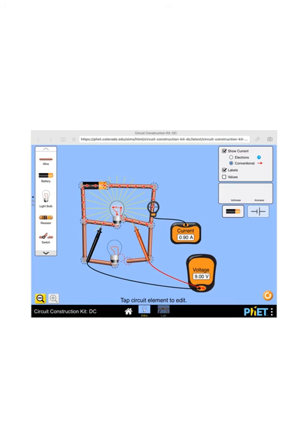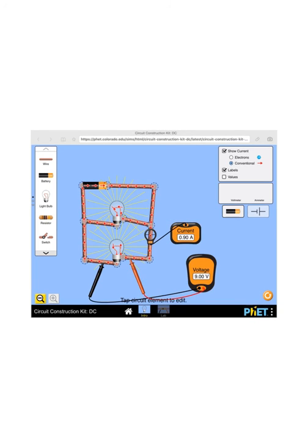Well, let's connect the second light bulb. The current has changed. It's gone from 0.9 to 1.8, but the voltage hasn't. In fact, if I measure voltage across this second light bulb, it is also 9 volts. My current's changing, but my voltage across these light bulbs is staying the same. Both light bulbs can still illuminate to the same brightness that any one did all by itself.